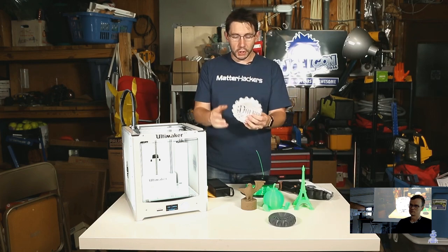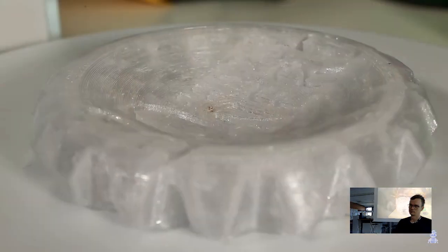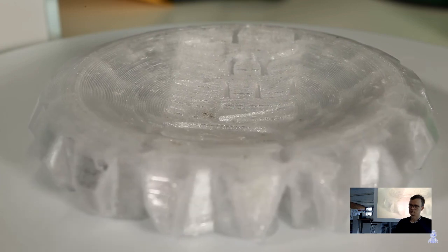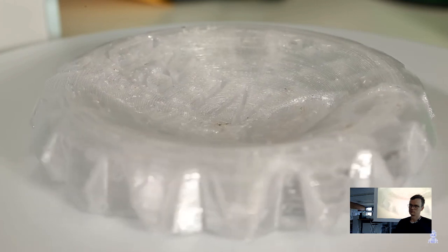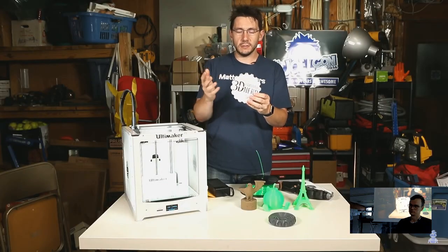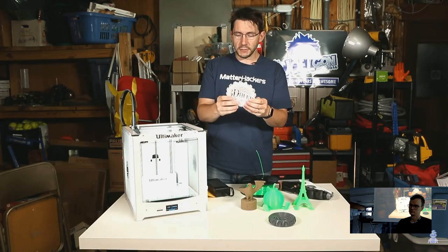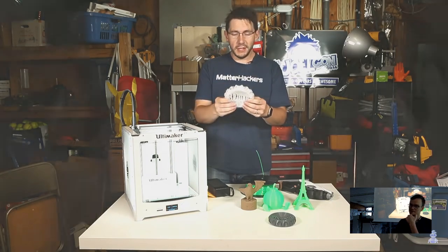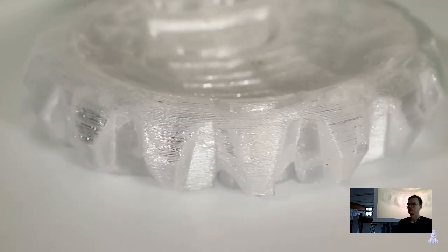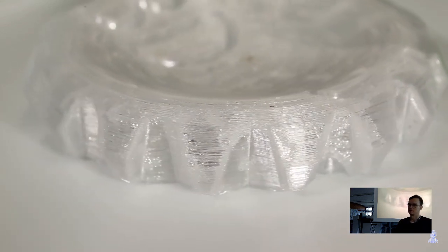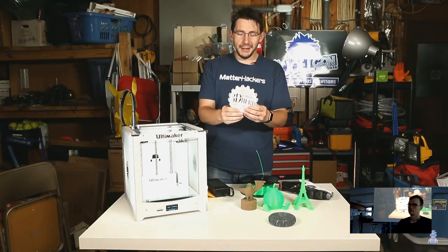The last model I wanted to show you is this maker coin, but it's using Angus from Maker's Muse's three-dimensional lattice infill. This was printed with ColorFab's HT material, and the material itself is a great material. It's got a good translucence. It kind of glows. It kind of shimmers because of the way the material interacts with the light. This material will grab on to your glass build plate. I highly suggest adding down some EVA glue just to guard against it, because when I removed this coin from the build plate, it also took tiny bits of the glass bed with it. And so that's why I flipped my bed upside down.